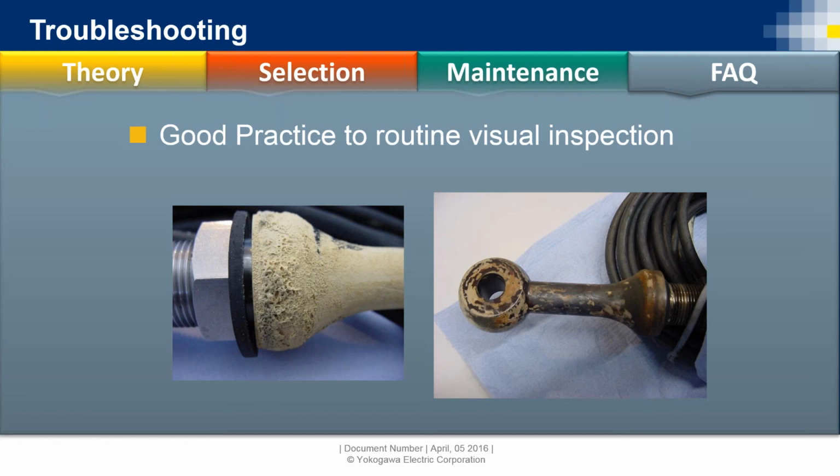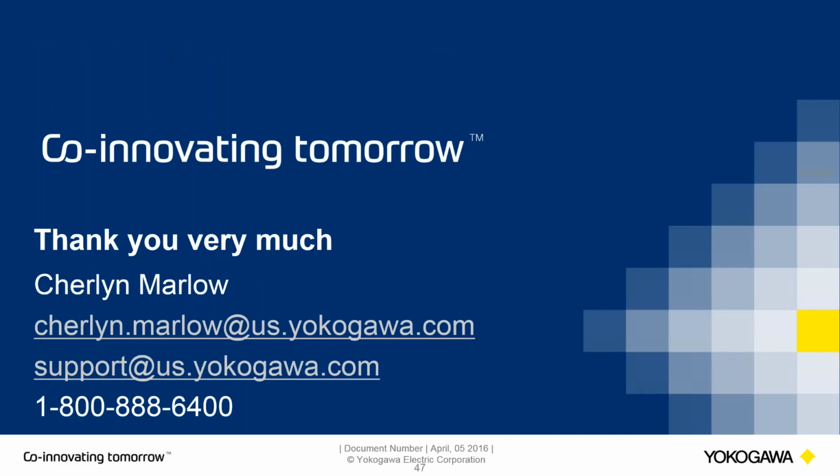And these are pictures of two last year where they finally failed after 10 years, and they said it's not working. They pulled it out and sent it to me, and that's the condition the sensor was in. There's a reason why it's not working. That's supposed to be brown, or a PEEK gray, or I guess a tan material instead of black. And it's the same thing: the process chemical was attacking the sensor material. So if PEEK is not compatible, like in sulfuric acids, we need to make sure that we use Teflon. So just be sure to check them and make sure we pick the right materials for the right sensors.